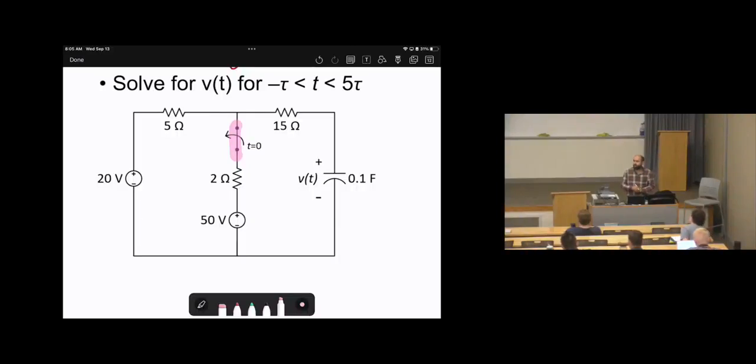Then the second thing you need to look at is to determine whether it is an RC or RL circuit. There are resistors, and look, there's a capacitor. So it is an RC circuit, and in this course there should be only a single capacitor. We have only a single capacitor and a switch, therefore it is an RC circuit. In an RC circuit, even if you need to find the currents, you need to find the voltage first. After that, you can calculate the currents.